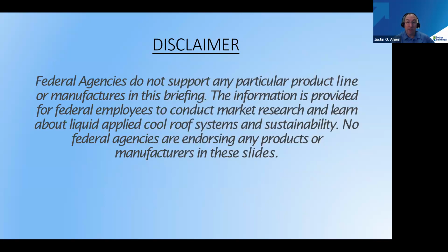Cold applied liquid monolithic seamless systems, no hot permit requirements, no safety concerns or fire or specialty tools, fully bonded to the existing roof structure, no air gaps, ASHRAE climate zone compliant. It's a UV stable product, no or low VOC below established limits. All membrane products meet this goal. Cool Roof Rating Council rated product on top, which is silicone, which was UV stable, high solid silicone, 2 times thicker than industry standard. Single ply membranes are 20 mils and IPP products are 40 mils.